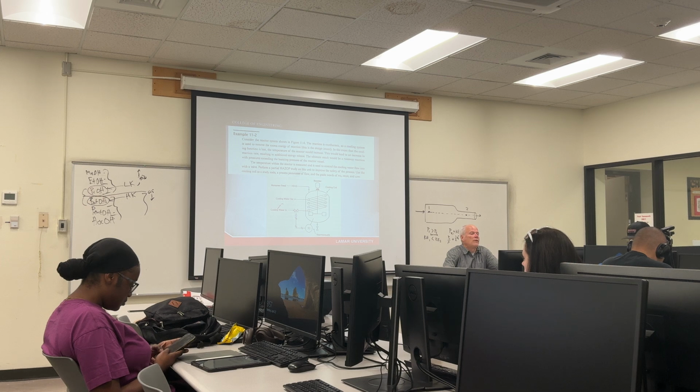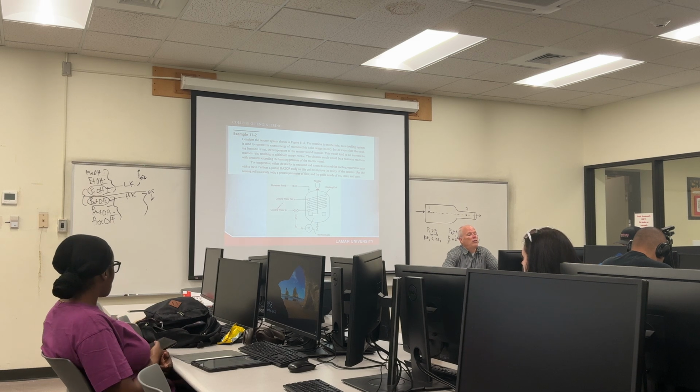So they want to do a partial HAZOP using the cooling coil as a study node. For the process parameter of flow, the guide words are no, high, and low. No flow, high flow, and low flow. So we've got cooling, you see the cooling coil up there, and we've got cooling water in. What happens if there's no flow?